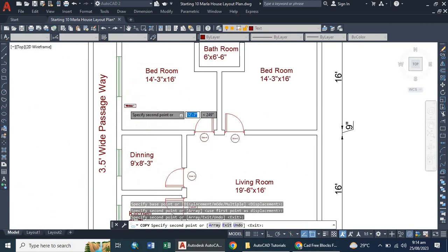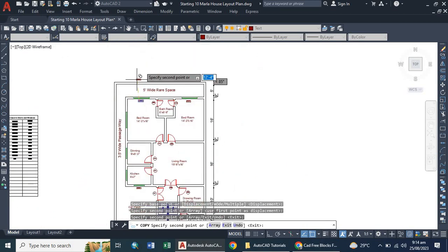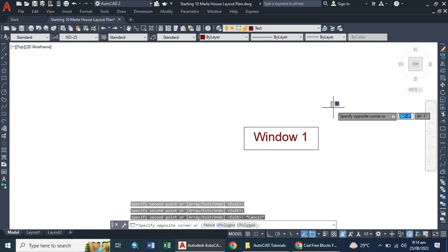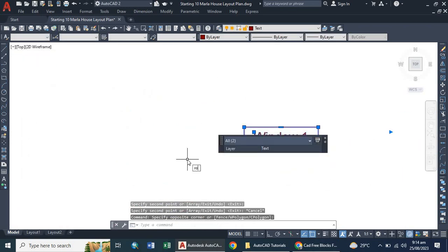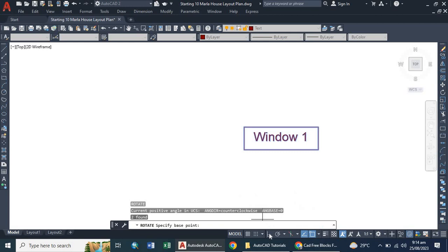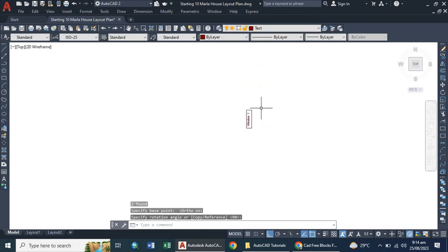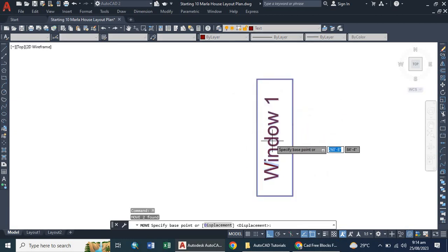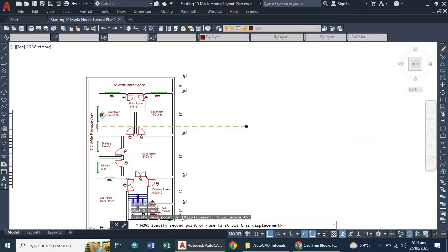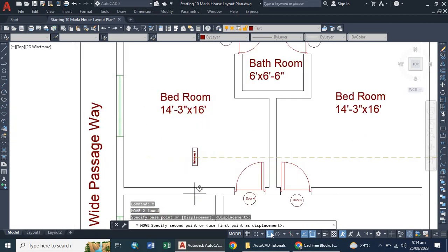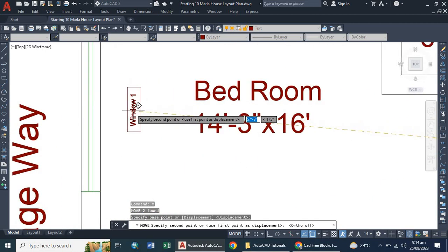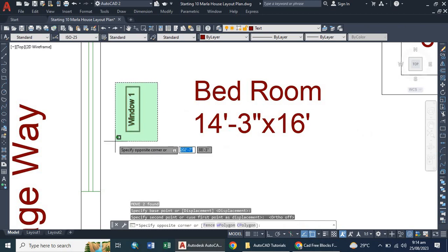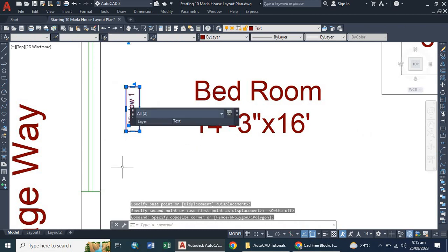Now, for these three windows we are going to make a vertical. For example, I'm going to select this, I'm going to rotate this, and I'm clicking on this ortho mode, and if you select your base point you can do this vertical in this way and move this to these three windows. Now I am again going with these windows and turn off this ortho mode, as you can see here. Otherwise your drawing will go only in 4 directions.